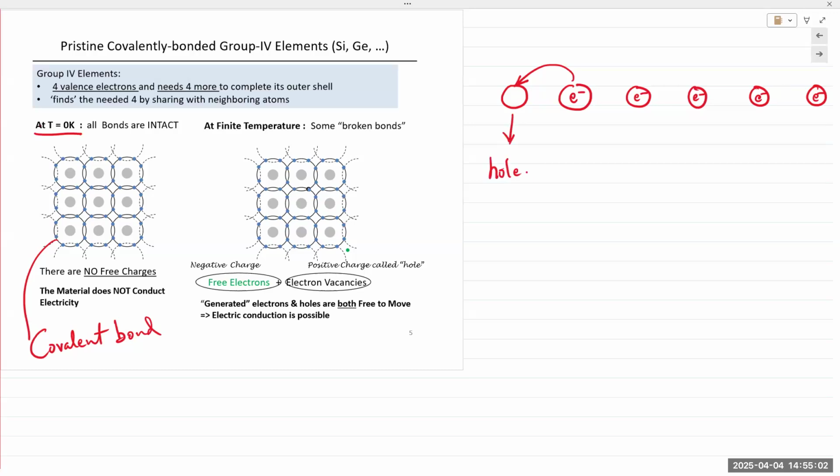Now, in semiconductor physics, when we deal with these devices, we refer to electrons and we refer to holes. So holes are just empty spots that are created because an electron has moved away. But it helps to treat the hole as a subatomic particle in its own right. Okay, so throughout semiconductor devices, semiconductor physics, you will come across terms that say electrons are moving and holes are moving. Holes are carrying some charge, electrons are carrying some charge the other way. And so it helps to treat the hole as a particle in its own right.